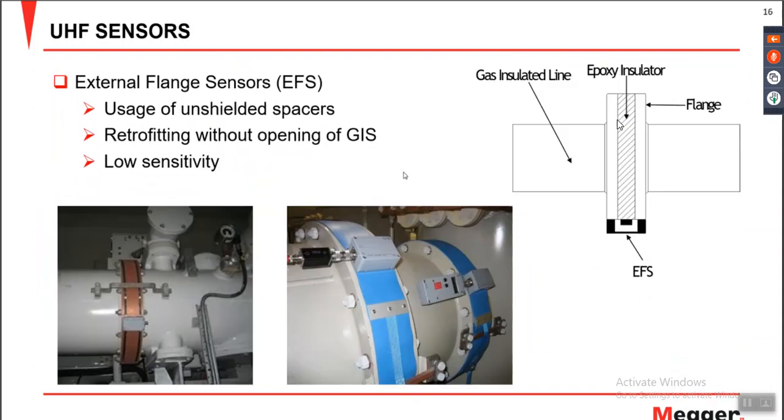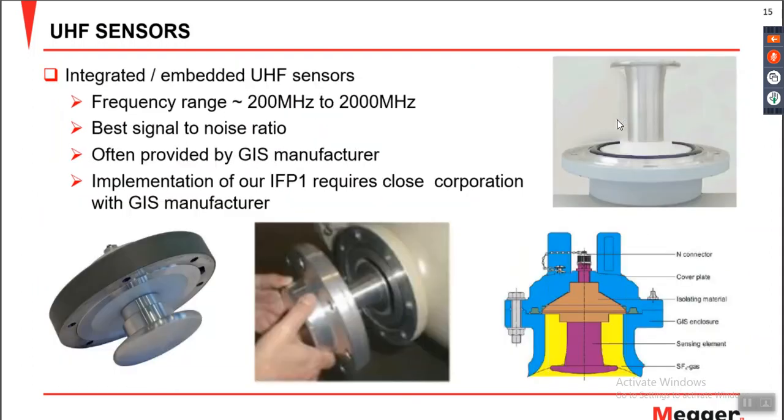Yep, thank you, Kiyor. This one is related to the 500 kV induction question. Maybe he is asking whether it could affect the measurement if we have induction at a 500 kV system. The answer is no, because when we are talking about induction, it is almost like corona or a high voltage stress, and it is almost in air.